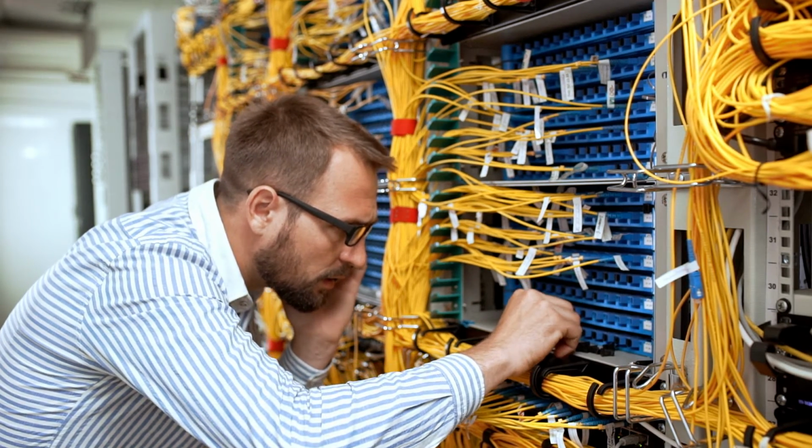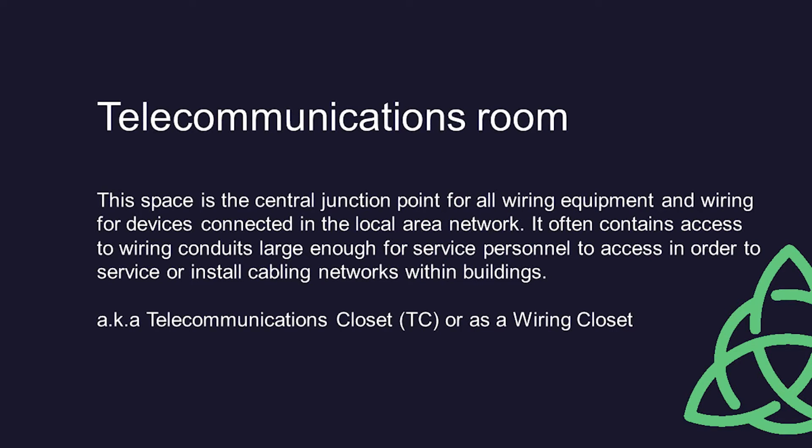It is strongly recommended that the carrier entrance facility is a standalone room to meet carriers' security and network integrity requirements. Furthermore, carriers require that their entrance facility is directly accessible from a public space or basement car parking space. The door is recommended to be keyed to meet the carrier's requirements. This greatly assists carriers. They do not want to waste time and resources trying to organize and coordinate access to back-of-house areas, which are normally access controlled, especially during fault rectification situations.